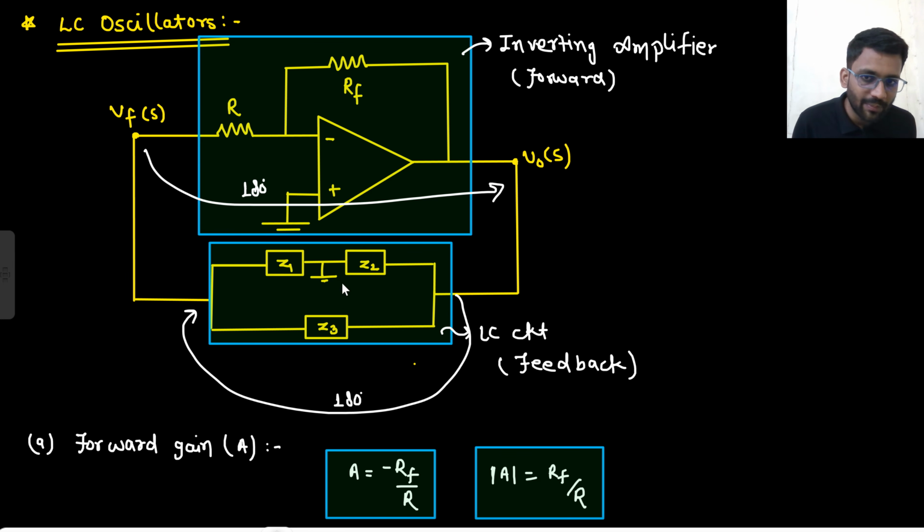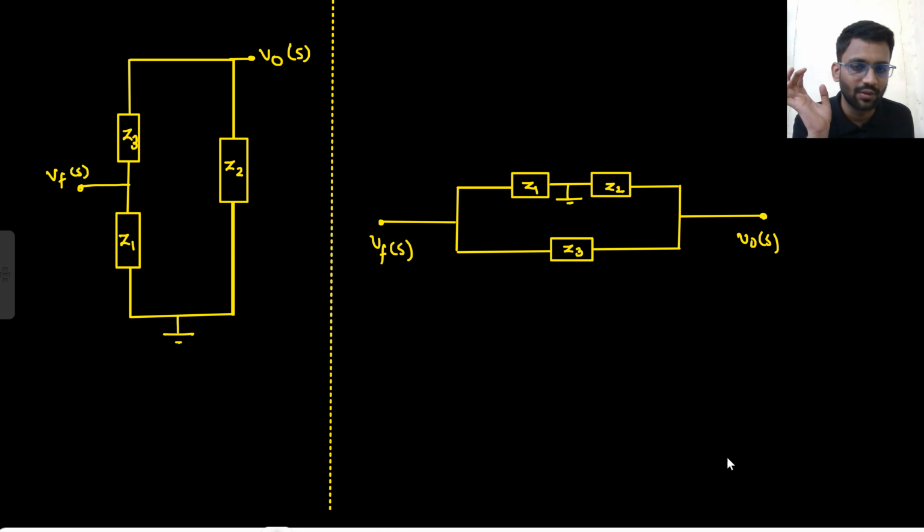Now in this ground there is 0 ampere current, so certainly there will be 0 ampere current in this ground as well, because the ground is the same, right? It's not that one ground is taking up 0 ampere current, so the other will take up some 2 ampere current. It's not going to happen. If from the ground 0 ampere current is going out, then from here as well it would be 0 ampere only. So if the positive terminal is driving 0 ampere current, then this will also drive 0 ampere current. Say yes or no. So this current I can say would be 0 ampere.